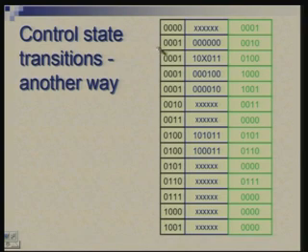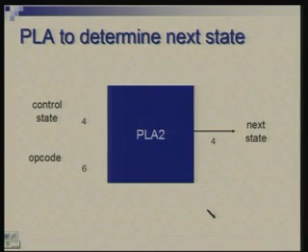Each of these will correspond to a product term. For example, what you are saying here is that if this is 0, 0, 0, 1, 1, 0, irrespective of any value of this, and 0, 1, 1 here, that should be the output. Okay. And so a term like this expands to 2 terms in case of a ROM. Things like this will expand into 2 raised to power 6 or 64 terms, and so on. So, that is why PLA representation will be much more compact here.